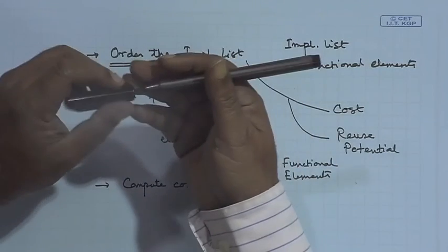So, usually the problem that occurs in this sort of solution for any CLP solution or for many of the AI search solutions is that the search space is very large. So, you have to do some look ahead and do some pruning, just like branch and bound. You see that if I make this selection, if I follow this particular path, then I am already exceeding my cost. So, there is no point proceeding in that path any further, and so I will select the other paths. In that way, different algorithms can be applied once we formulate the hardware software partitioning problem in a suitable way, as we have done today.